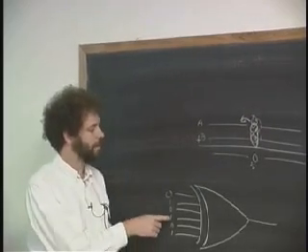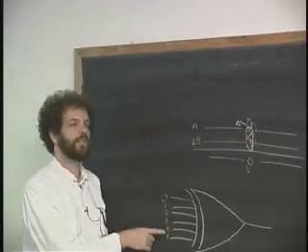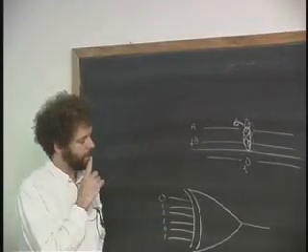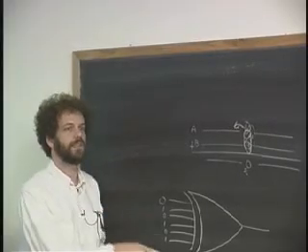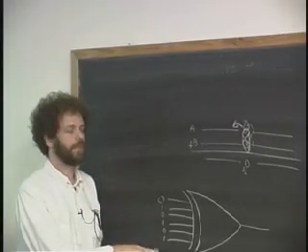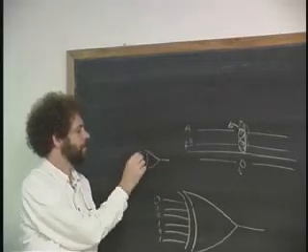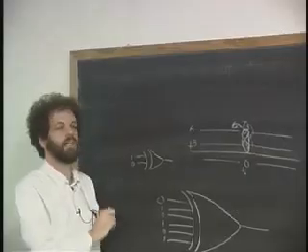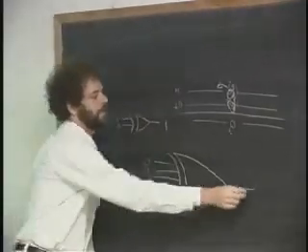It's counting how many ones there are, okay, and it's seeing if the number of ones is odd or even. Now, is the number of ones here odd or even? Odd. So what is the XOR of all these things going to be? Well, you can think about it in the easy case where there's only 2 bits. Here's another one where it's odd. What's the XOR of 0 and 1? 1, okay. So that's 1.